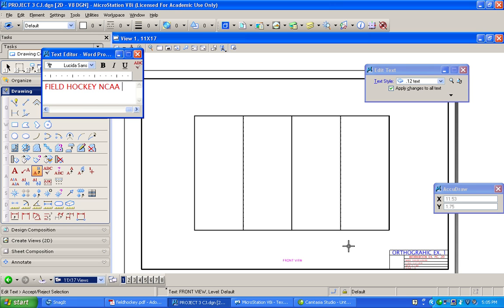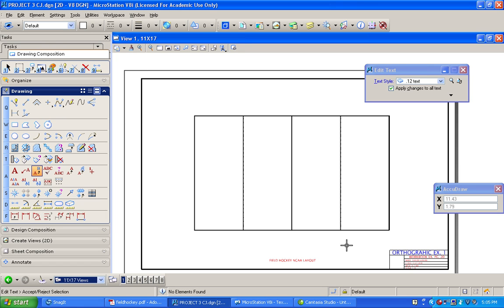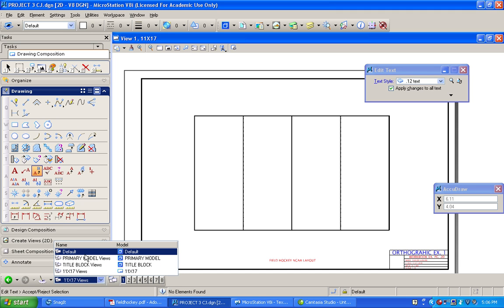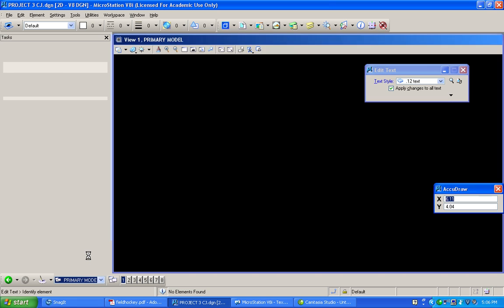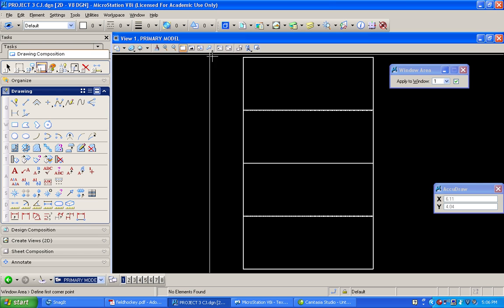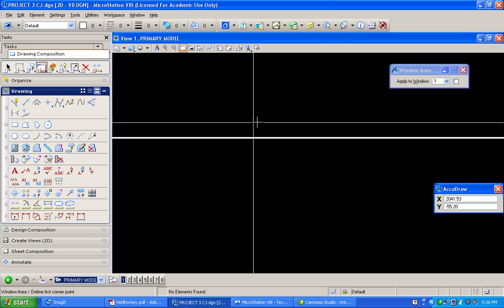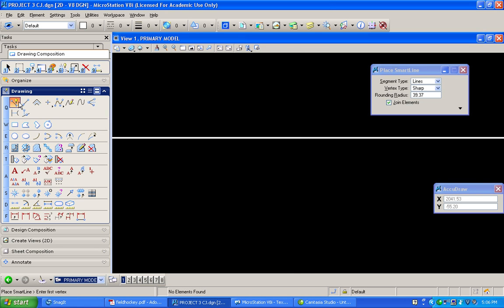and we'll just go in here. We know we can find a center point. So we know our goal is 12 feet wide, 4 feet deep. So there's a center point. If I just middle mouse button here and hit O, if it's 12 feet wide overall, we just go 6 and left click. Looks like it was 6 inches. Middle mouse button, O, 6.